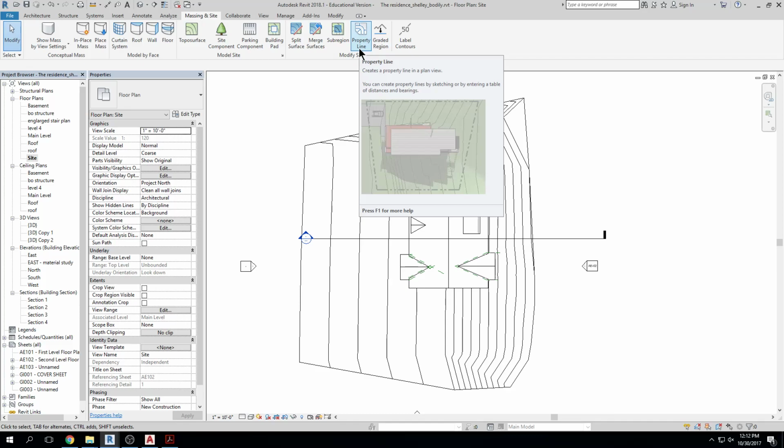I'll start talking about detail lines through all the different drawings we're going to be doing. But essentially, detail lines are just dumb lines, meaning they don't have anything connected with them, like a structure or a designation or a definition, and we can draw them in to represent something. I would say about 50% of the time I use actual property lines, and 50% of the time I just fake it with detail lines for my property lines.